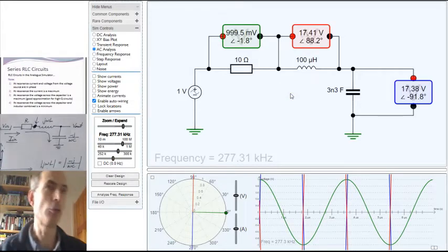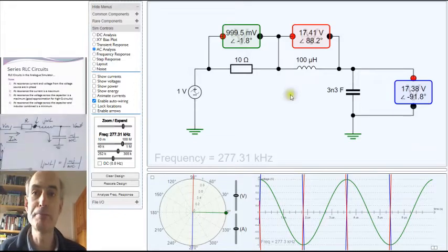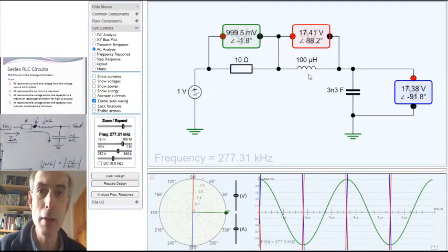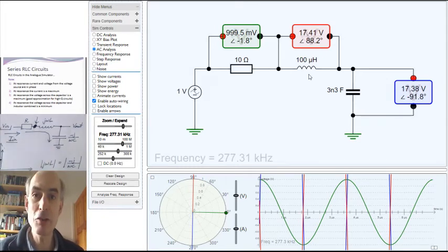But you can work out what the resonant frequency is using the formula derived before. Do remember, of course, that the capacitors and inductors that you use in the lab will have a fairly wide tolerance of 10% each or so, so the resonant frequency that you measure with your real components won't be the same as the ideal resonant frequency that the simulator suggests.